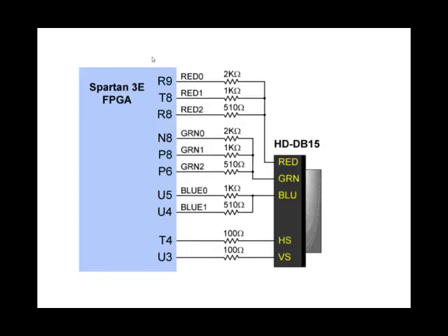Your FPGA circuit does not have the ability to generate an analog signal. The outputs of the FPGA are either a 1 or a 0. However, circuitry outside the FPGA has been added to allow you to generate these analog signals from a set of digital signals here. These are shown by the resistor network. This carefully designed resistor network allows you to create a limited set of analog signals by driving the color signals with 1s and 0s.